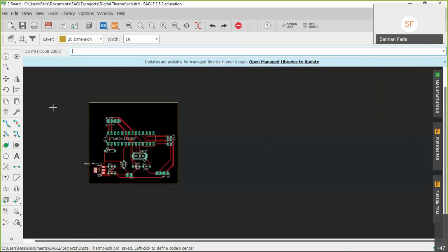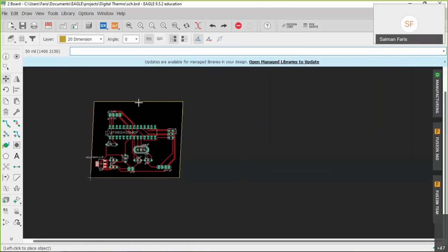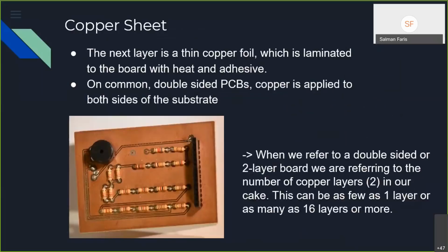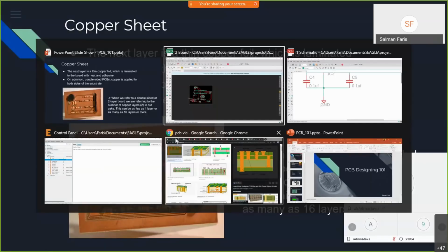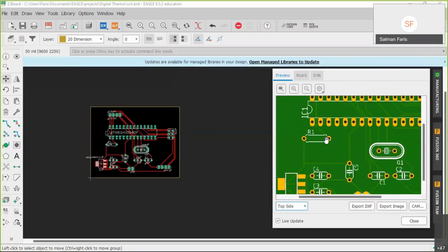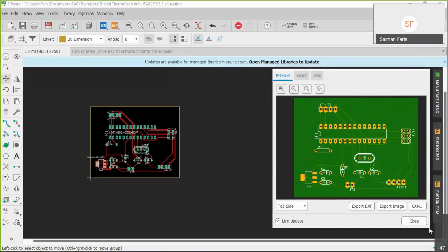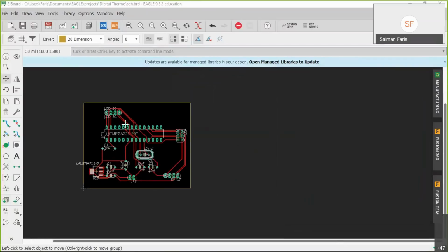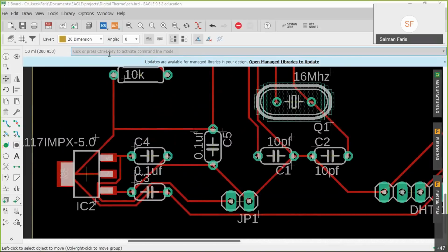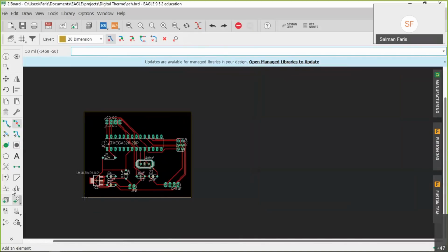Okay. And another thing is it's better to have a ground plane. It's actually better for stability. What they are doing is milling the traces from the copper clad. So here you can see they need to mill everything from here. This is a copper sheet. They are going to mill everything, and only the remainder will be the traces. So we can save the process by adding a ground plane. It is also very good to improve the stability of our PCB. For that, I just need to remove all the ground planes first. That's also fine, right? So I'm going to make a polygon.